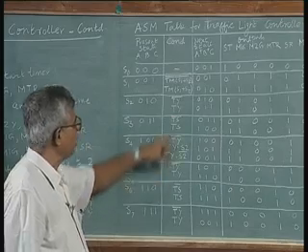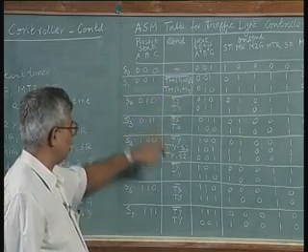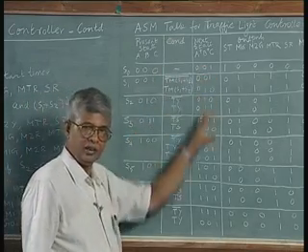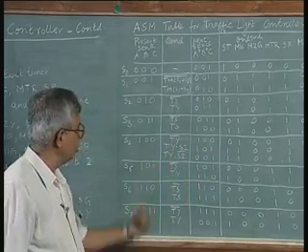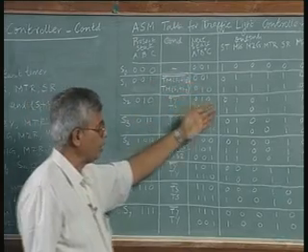The conditions are very simple: timer yellow not completed, completed, timer side not completed, completed, timer main completed, not completed. Sensor S1 S2 both are marked in this first stage, whereas only S2 is monitored in the second stage. Based on that they go to the next state. We drew this ASM, you can correlate this with the ASM that you drew, and from this state the condition to the next state and what is the output in each of these states.